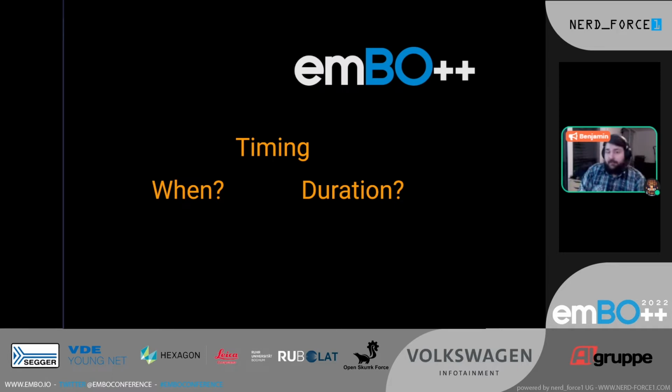there's something called a brownout detector. The brownout detector will notice any undervoltage condition and reset the chip. Usually this is meant as a countermeasure against the embedded system running while it is running low on battery and potentially misbehaving. In our case, it will get in the way of our attack because we undervolted. So we want to keep the glitch short so the brownout detector does not trigger. Also, if you glitch it for too long, you might corrupt more than a bit of the state, which can lead to a condition that just cannot recover. So let's look at when.